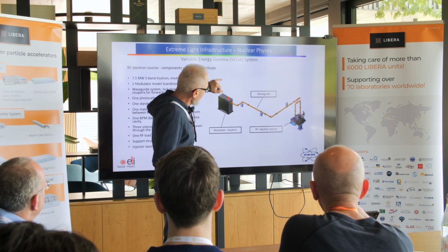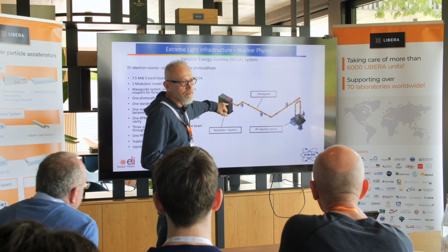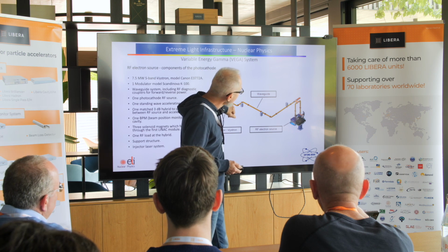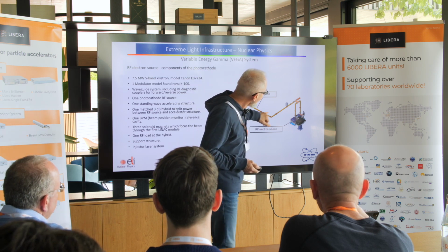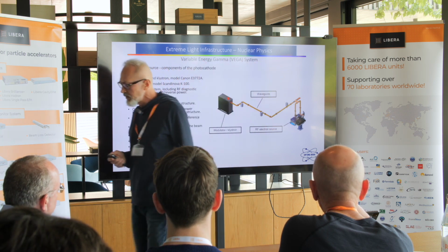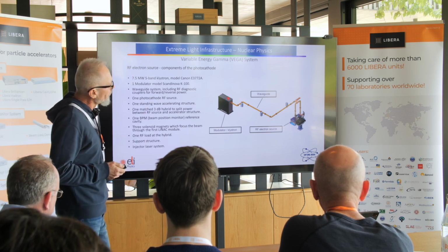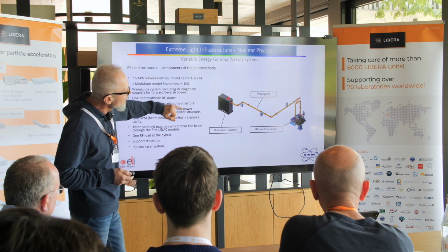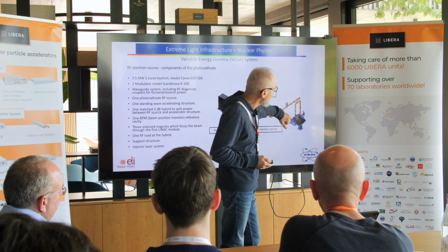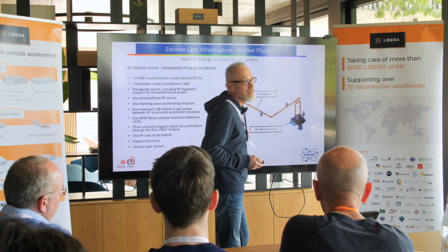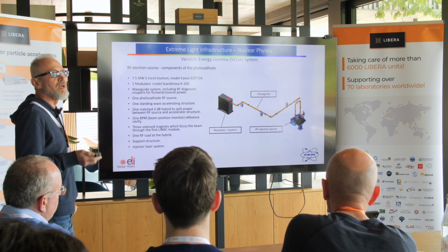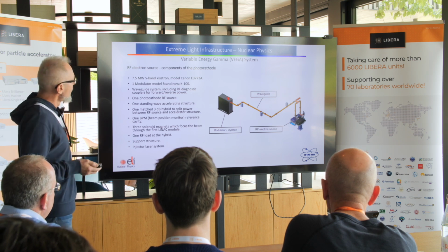After the RF S band 2.8 gigahertz pulse signal is generated, it will follow some waveguides and arrive at one hybrid, a 3 decibel hybrid, where the power pulse is split in two sides. One side arrives at the electron beam generator, and the other side arrives at one standing wave structure, which will amplify the energy of the beam up to 13 mega electron volt.